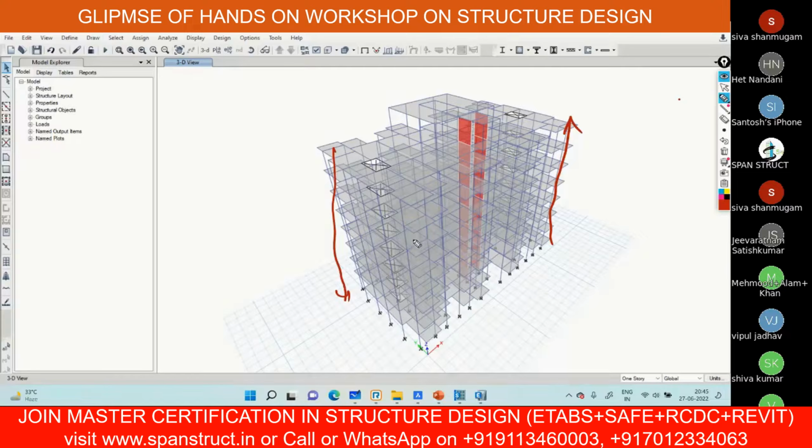Yes, this is when you are modeling a beam as a 2D element. See, a beam or deep beam: when you're giving floating columns, in that case, where the beam column will get rested. Floating column means it will not come from the base. The column will not be there; the construction of the column will start from the beam only. So in this case, where the deep beam comes, you have to give it as a spandrel.